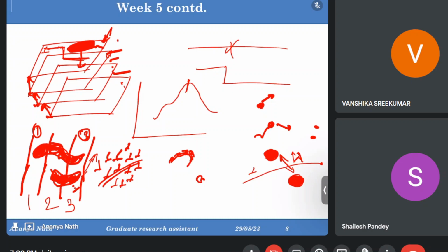And both cross slip and climbing are needed for us this time because we really want to move the dislocations, because we know the dislocation density is so high that even if we allow the dislocations to move forward in a particular lattice, they will lock themselves after some time because of their own nature of finding a low energy configuration.